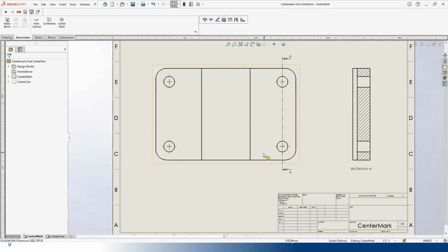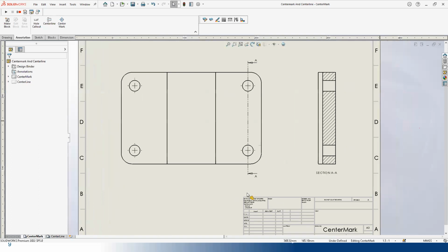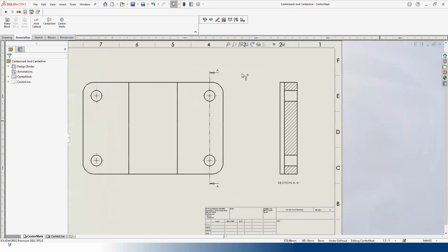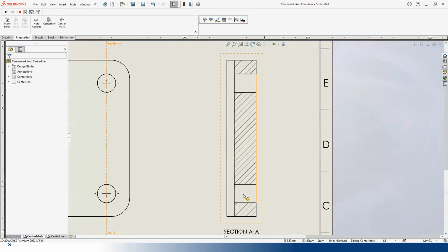Now, assume this was our front view and we were seeing the holes and the circular edges are visible. When we are looking at the side view, and assume this is the only view available to us, unless we define something for these cutouts, one can assume these are square or rectangular cutouts.